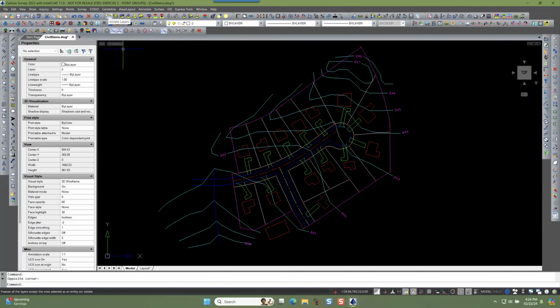And that is a layers toolbar that has these commands on it. It's got isolate layers, restore layers. It's got freeze layer by pick, meaning if you just click on something, it freezes the whole layer immediately. Or it's got freeze layer, where I can pick a bunch of things and see the items that I pick and it highlights them. And when I'm through picking, it then does the freeze.